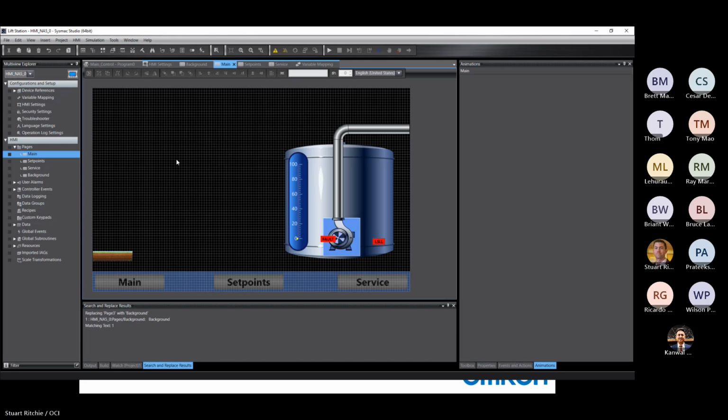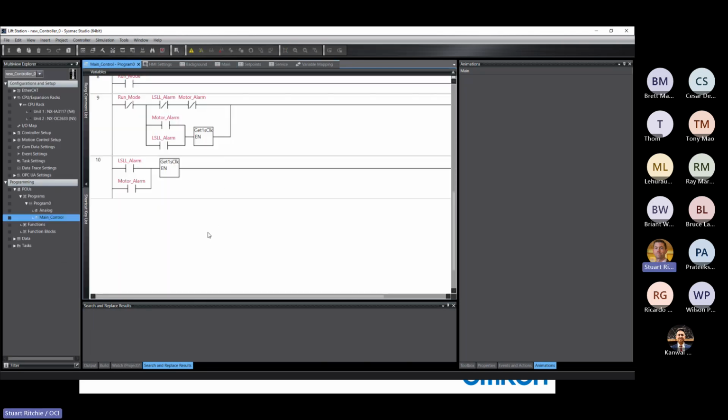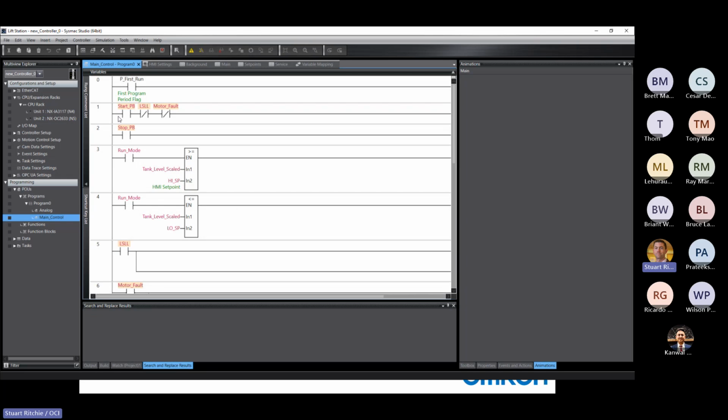Good. So the next thing we'll add to the HMI is going to be start, stop, and reset buttons. Now, if you've tried to do this before with a PLC, we cannot write to a digital input variable. We could add it to the HMI, we could try, but it's not going to work because the digital input state is going to overwrite the variable at the start of every scan cycle. So what we'll do is we'll have another start push button variable in our PLC that only the HMI uses, and it's going to behave in the same way as our start push button.